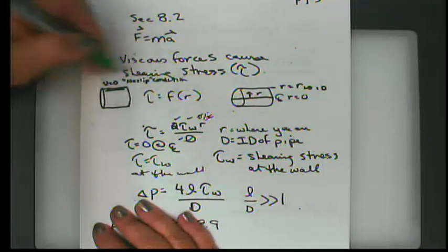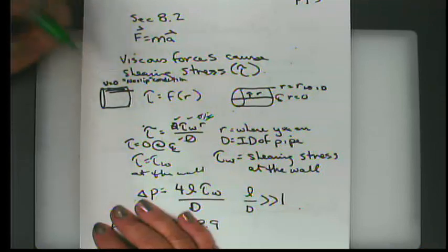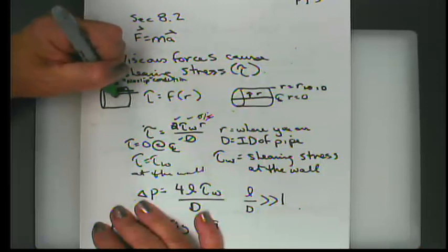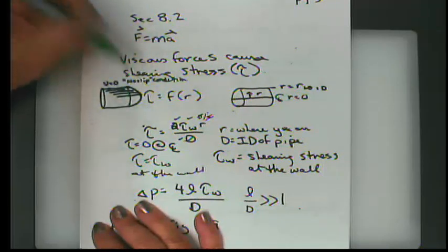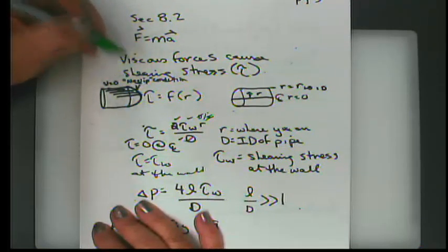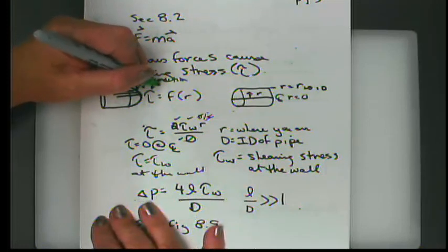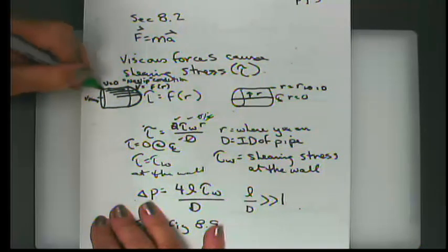Right? The next lamina moves a little bit faster, but it slides against the lamina at the edge of the pipe. And we continue onward to where we have a 0 velocity at the wall of the tube, a maximum velocity at the center line, and the shape of the velocity profile is essentially parabolic. So the velocity is some sort of a function of the radius of the tube, where the velocity is a maximum at the center line and the velocity is 0 at the wall.